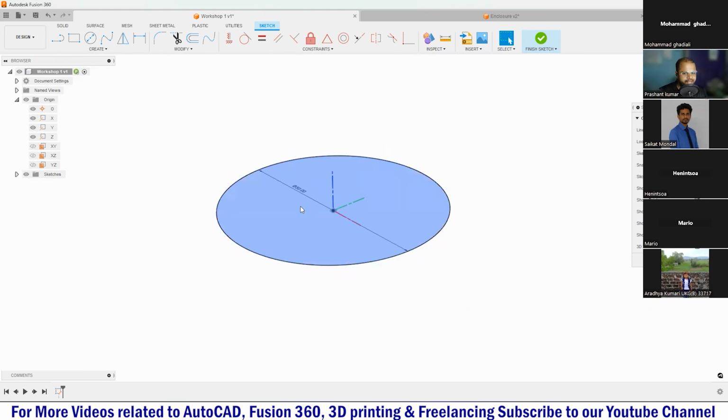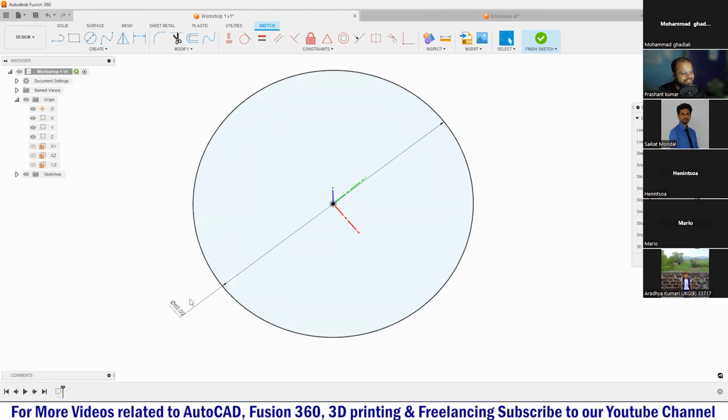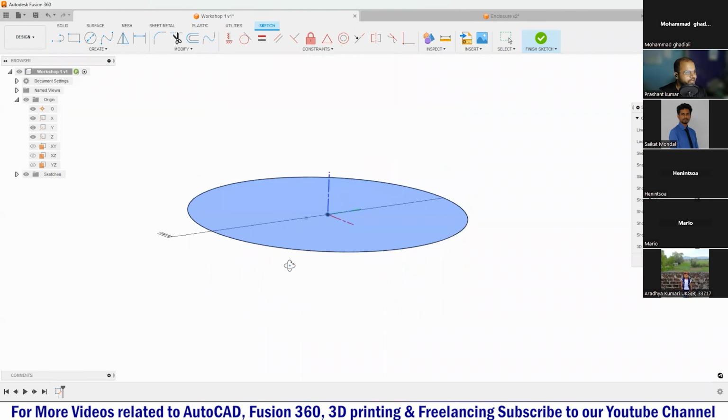So, and all the time guys, if you want to edit these dimensions, this 50 dimension that you had just created, here you can see. All the time, if you want to edit this dimension, just double click, and let's say I don't want 50 at this stage, I want 60. Somehow accidentally I had written 50, so I will just type this new dimension 60 and press enter. Here you can see it is getting updated instantly, guys. You can see the dimension is getting updated instantly.